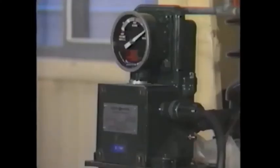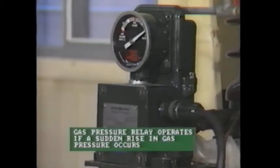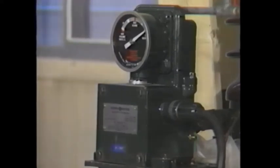The gas pressure relay, as its name implies, operates if a sudden rise in gas pressure occurs inside the tank. For example, if heat is generated in the oil by an electric arc. These relays are quite sensitive and can often detect a fault before it develops severely enough to operate the differential protection.